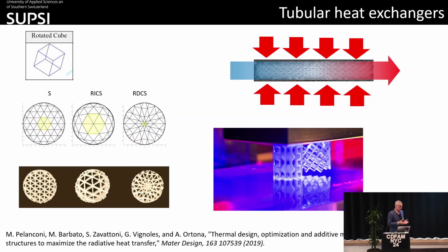You just heat the first layer of the fluid touching the inner walls of your tube. As soon as you put in a porous body, you start increasing the mixing of the fluid on one side. You have more surface for heat exchange, and you also have guides for the heat to be transferred from the outside to the inside by conduction.